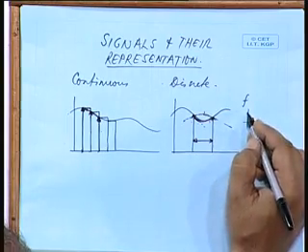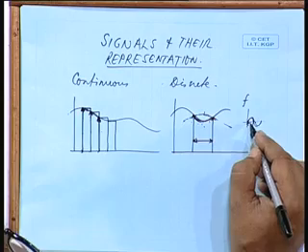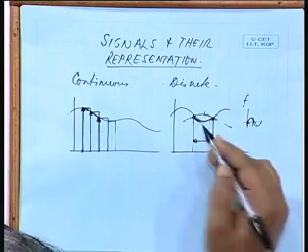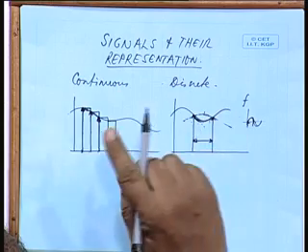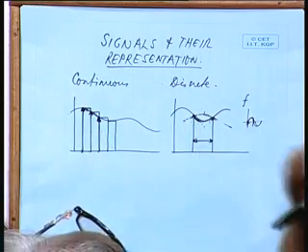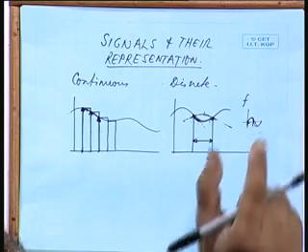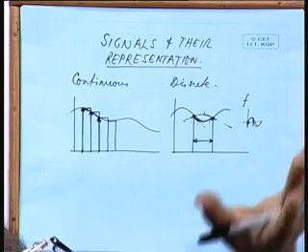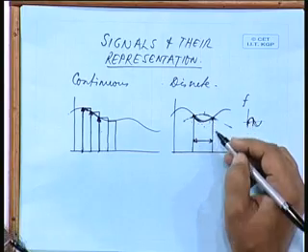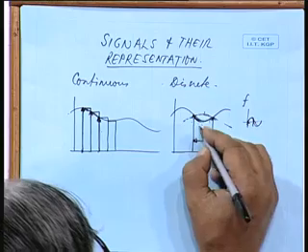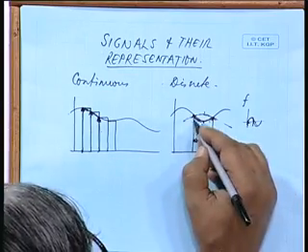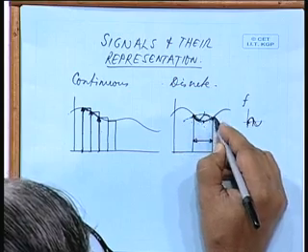So, half the length means twice that frequency that is present. So, the maximum frequency that is present, that means the maximum number of changes that may occur in the original signal, twice that frequency, if I sample the original signal at that frequency, then only I will be able to just recover this point. Okay.